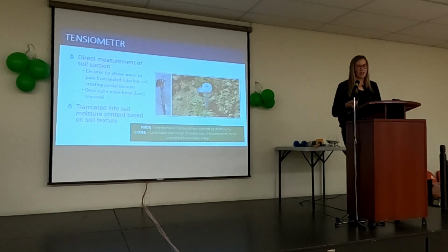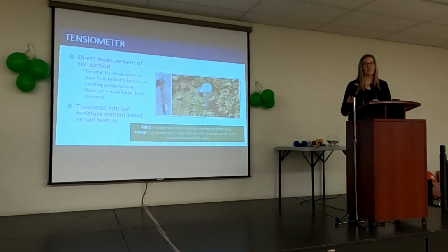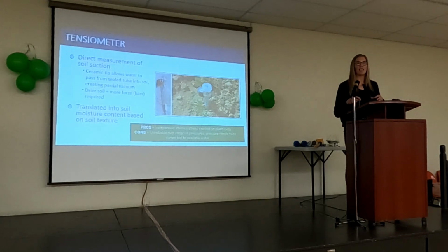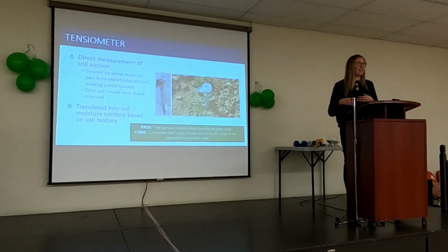So there's going to be that time needed to convert those pressures into available water. So I guess also not ideal for that extra step. And then these require some maintenance. You do have to monitor them throughout the field season, because if the water evaporates out of that plastic cup at the top, then you lose that suction pressure. So it is something you have to go around and make sure that these are all primed and full of water.